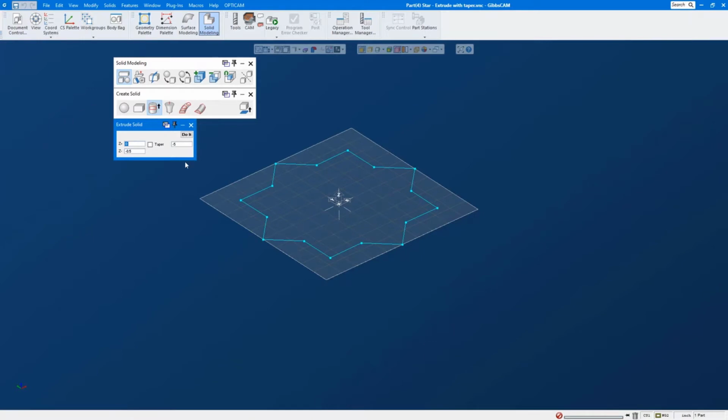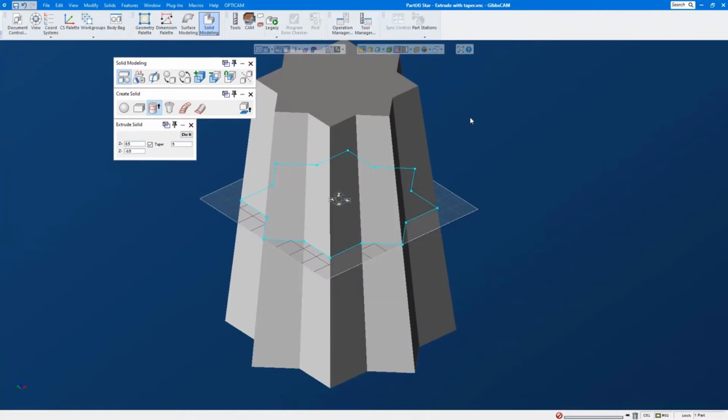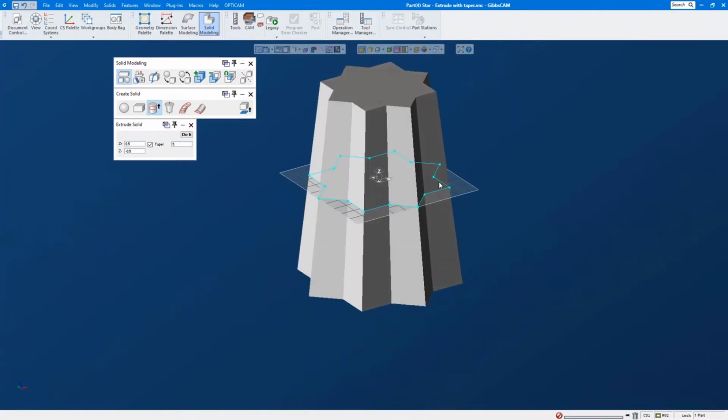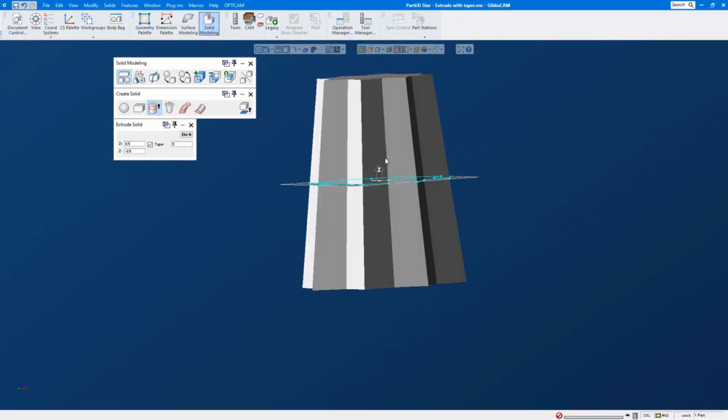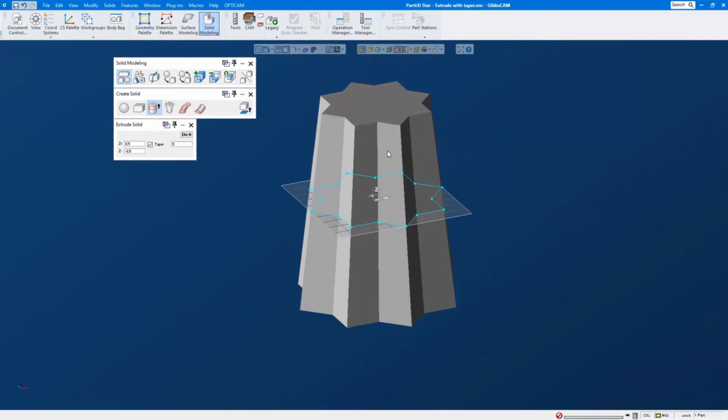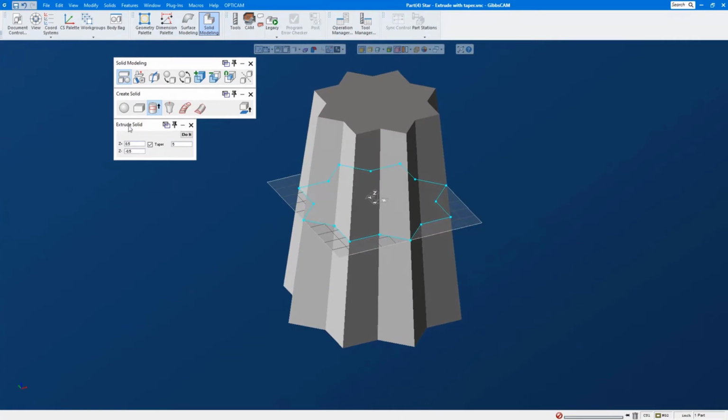So now we can go in both directions, and you switch on taper angle, pick your geometry, and it creates extrusion up and down from that location. This is also pretty nice functionality in the software. So this is new. You could only do one way, couldn't do both.